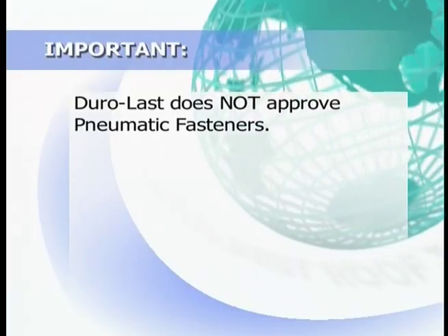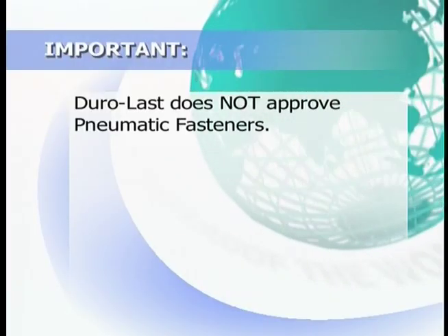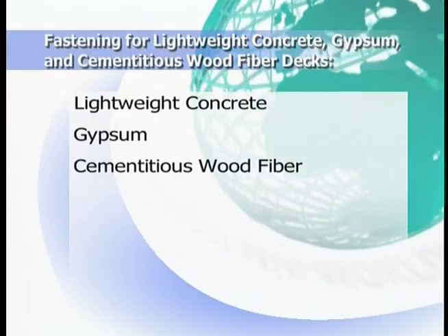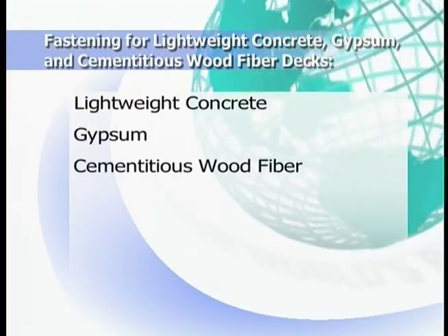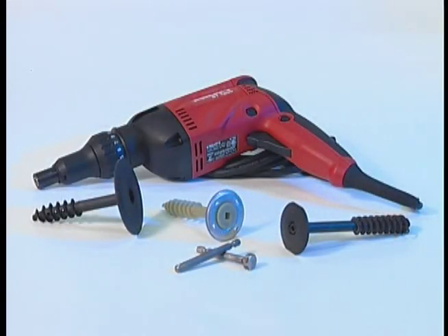It's important to know that in no instance does Duro-Last approve pneumatic fasteners. Now let's turn to correct fastening for lightweight concrete, gypsum, and cementitious wood fiber decks. For these kinds of decks, use the NTB, auger, or liquid auger fastener that Duro-Last supplies. They require a screw gun with a special driver. One driver is included in each box of fasteners.